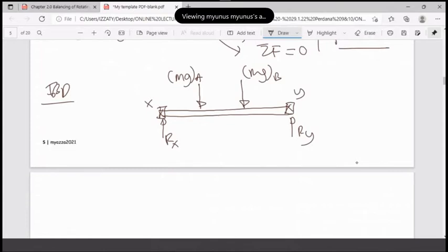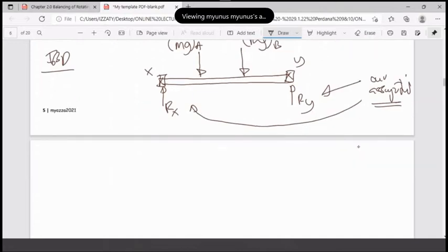As long as you know that this is R pointing upward, this B will be pointing upward. So this one and also this one is basically your assumption. We are assuming that it is pointing upward. Can we assume it pointing downward? Yes, you can also assume that it is pointing downward. It doesn't matter. Then you start using the equation of summation of moment about x, for example, equal to 0 for the equilibrium condition. So you have point A and point B, correct?